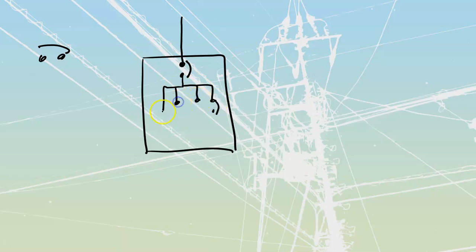We'll have different overcurrents placed inside of here based upon the types of loads that we are feeding out. The panel breaker itself is designed to protect the actual panel bus bars, which are the components that go between the actual breaker and out to the individual loads themselves.